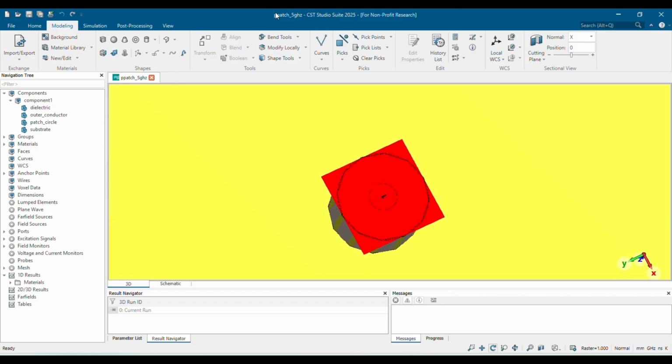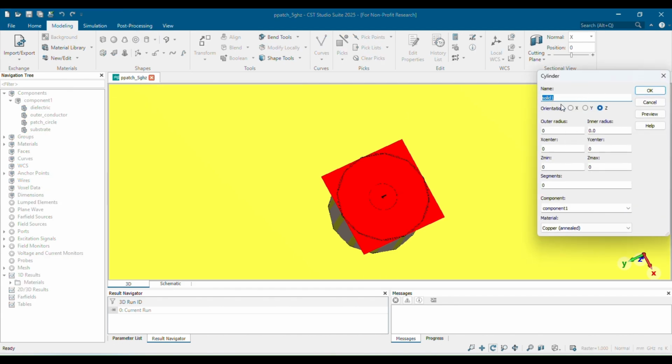Remember that for tweaking the position of the coaxial feed line, we start from, let's say, the center, and we can try r/4 and other values like r/6, r/3, r/3.5 accordingly, because from 0 to r the impedance varies from 0 to 200 ohms, and we have to make our antenna 50 ohm impedance. So here are some trials and errors that I have simulated.